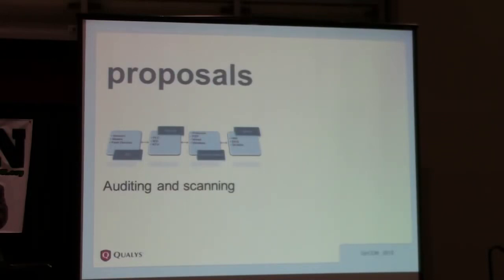For auditing, there are a lot of tools available. There is a free tool that I mentioned, but be very careful because SCADA PLCs, sensors, and whatnot are very low-powered devices. A lot of them will just crash or reboot even if they get a ping packet. So if they get something that they don't understand, they will crash. If you use my tool, there is a big disclaimer here: it will definitely crash something somewhere. It is written with all the care that it should not, but there will always be a PLC or a system which just cannot even handle ping packets or something like that.